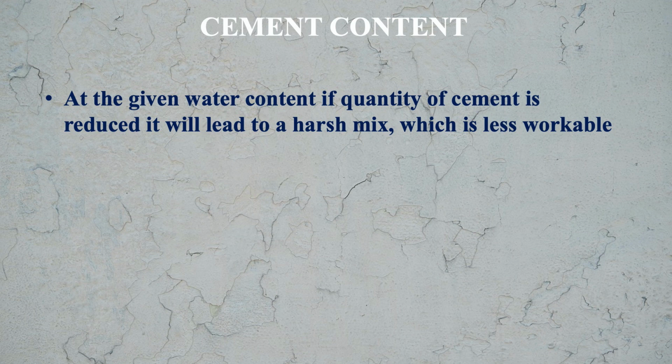Now let us see the effect of cement content on workability. At the given water content, if quantity of cement is reduced, it will lead to a harsh mix, which is less workable. Means amount of cement if you are reducing for a fixed quantity of water, then it will lead to the harsh mix.